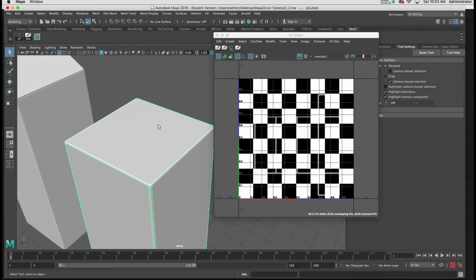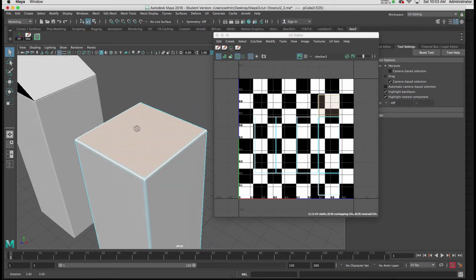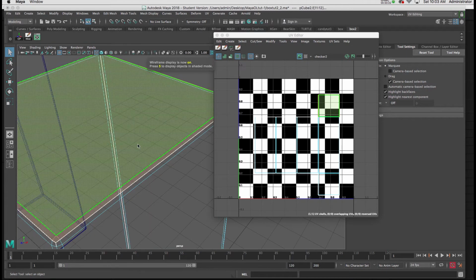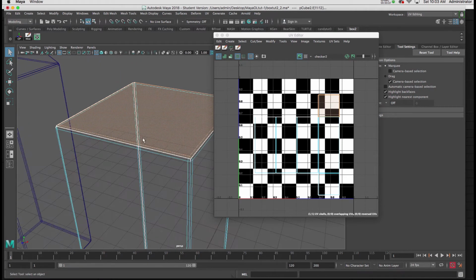With my box selected, I'm going to right click and choose face. I'm going to select the top face. Now I want to select the first row of the bevel edge as well. And I'm going to hold down the Shift key, and if I hit the close bracket for HTML, which appears to the left of the question mark, it selects the next row of polygon faces. So I'm going to zoom in and hit 4, and you can see now that those polygons are selected.